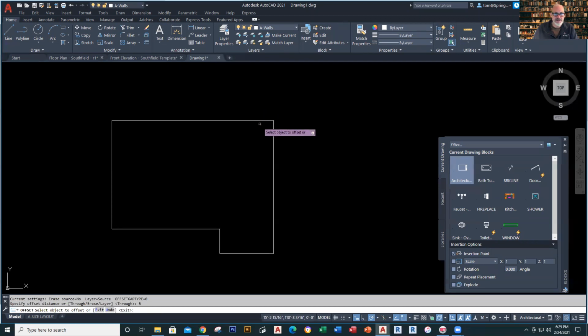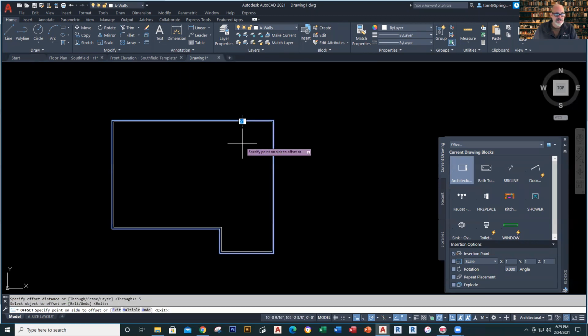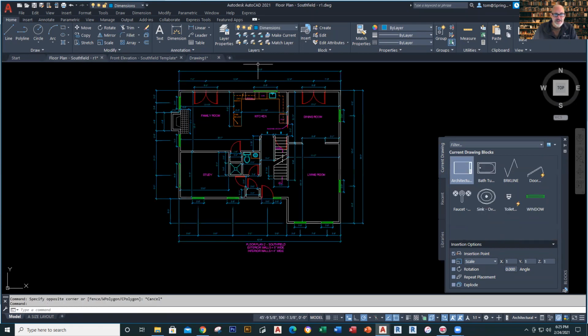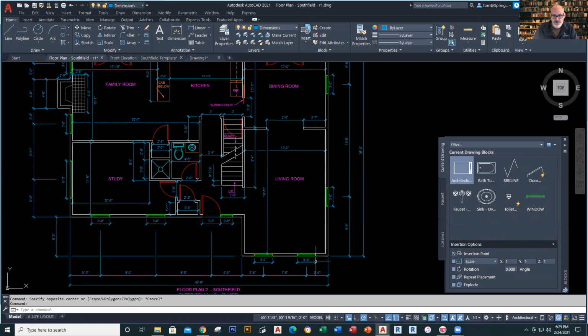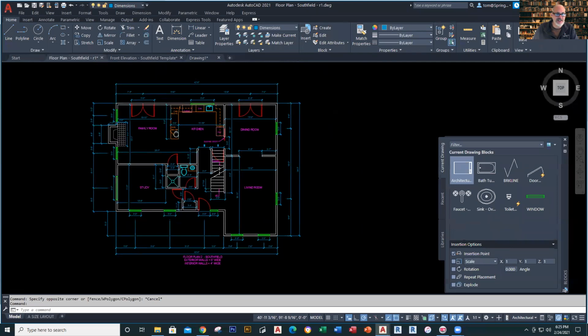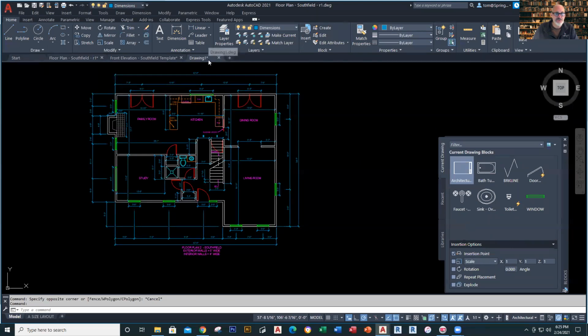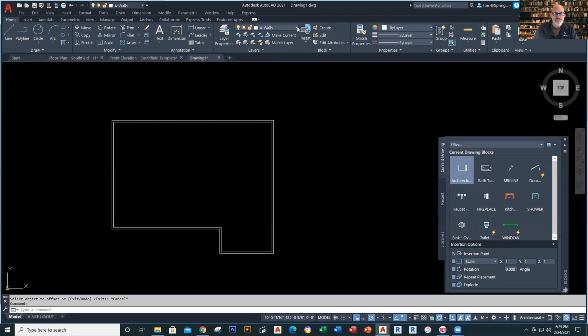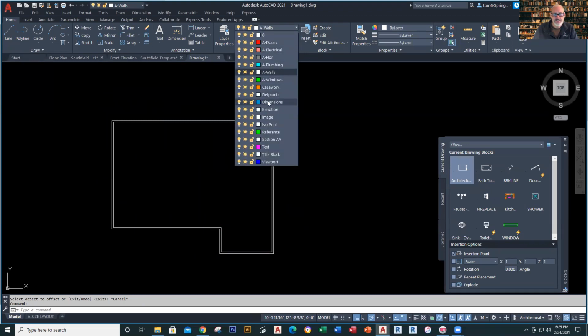I'll go ahead and click it here, and I'll go like this. So there are my walls. Okay, let me make sure they're correct. So I have 42 feet, 34 feet, and this is a total of 14 feet right here, and then 6'3", and then around. So let me make sure that I've got it so that I don't build on a bad foundation. So I'll go here, change it to dimensions.